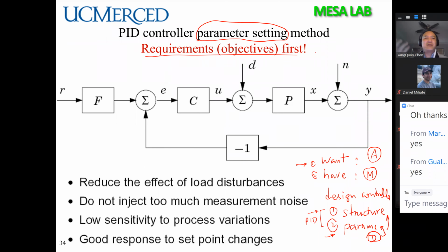So this is a typical control system. We talk about noise and disturbance after the plant or disturbance in front of the plant. So this is the plant, right? After it is N, in front of it is D. In a motion control system, this is at the position level, and this is like a torque or current level.